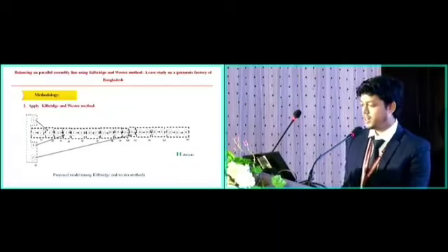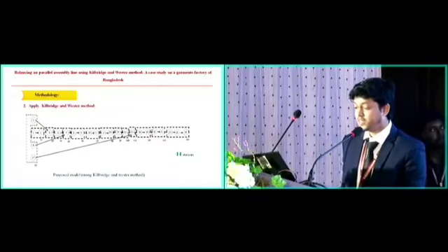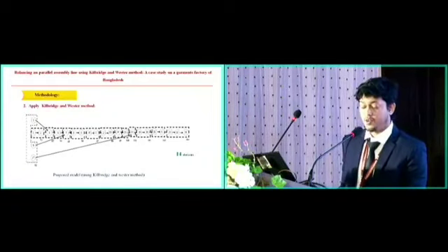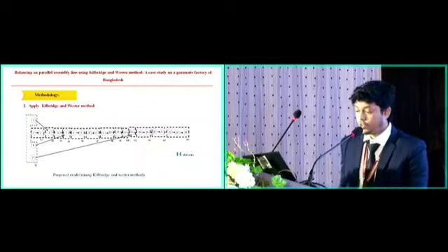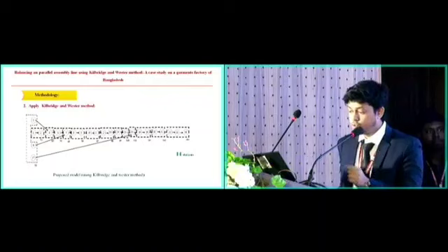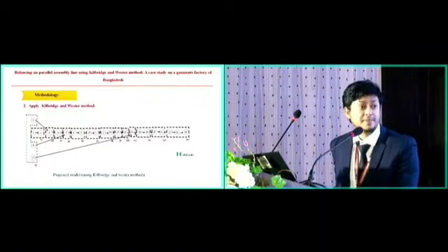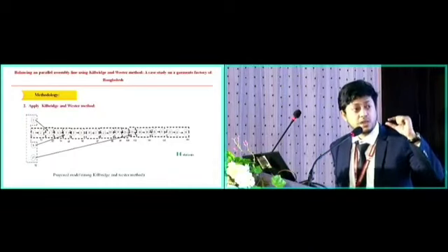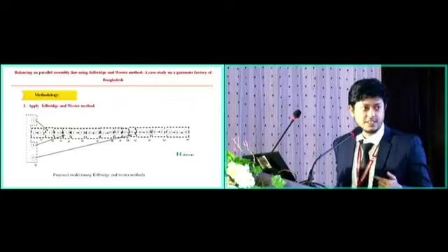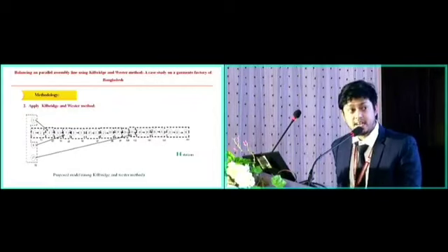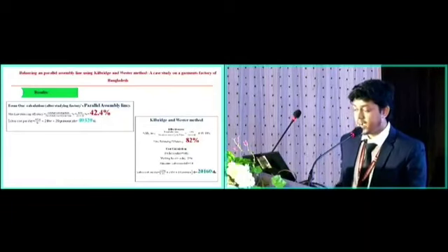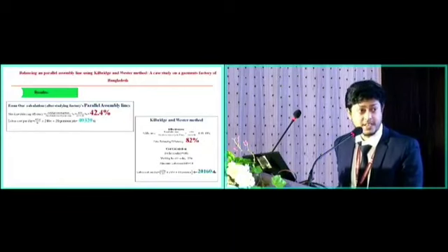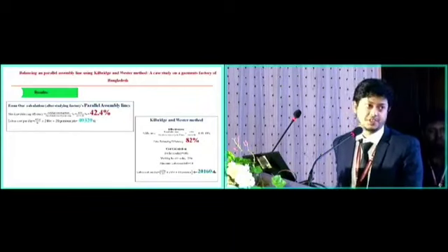Like here, we can see in stations 2, 3, 6, and 17 the process is done by one worker. In station 1, processes 1 and 2 are done by one worker. So one worker has to do those processes, 1 and 2, in 0.78 minute. So we have to assign stations according to the time limit, which is 0.78, one by one, and then calculate the percentage idle time mainly, which is 18%, and then the line balancing efficiency is 100 minus 18%, which leads to 82% efficiency.